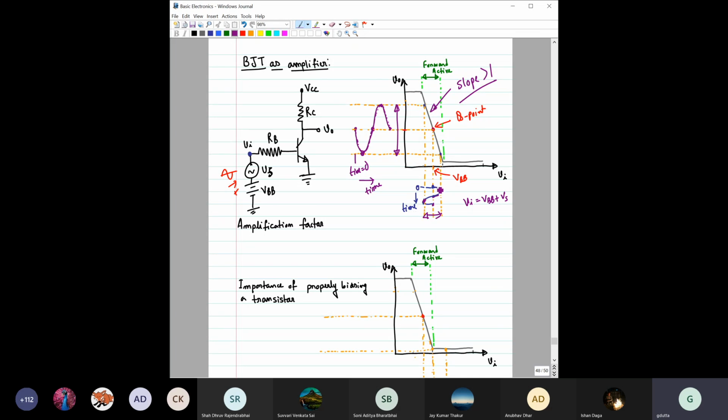So you can see this is the same sinusoidal signal, even though it looks like the time has changed. But that is not the correct way to judge this because it is a hand-drawn diagram. So you can consider the time axes are different. Let me write it here. Say this is 0 to T by 2, and this is T. Then here also it is 0, this is T by 2, and this time period is T. So this time period is exactly the same. The only thing that is changing is the amplitude. So you are getting the amplified version of the input signal.